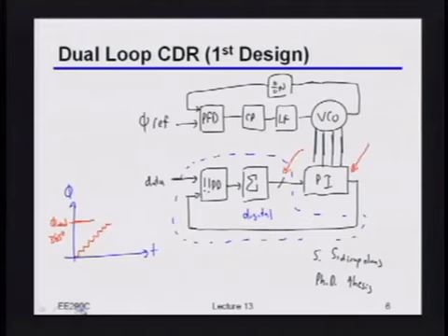And the basic idea is the following. What you essentially say is, let me use some sort of phase lock loop that uses a quote-unquote good reference clock just to generate the right frequency to begin with, or something that's at least close to the right frequency, okay? If I do that and I really do have a clean reference, then I can make the loop bandwidth for this PLL whatever it needs to be, based upon the noise I have on that reference versus the noise I would have had in this VCO. And again, that would tend to be something fairly high if you actually had a clean reference available, okay?